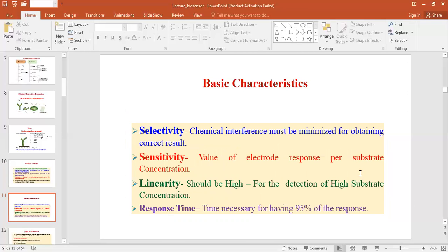So, in common practice, a signal processing unit should be included here, deducting a baseline signal obtained from a related transducer without any biocatalyst covering, and the comparatively slow character of the biosensor reaction significantly eases the electrical noise filtration issue.